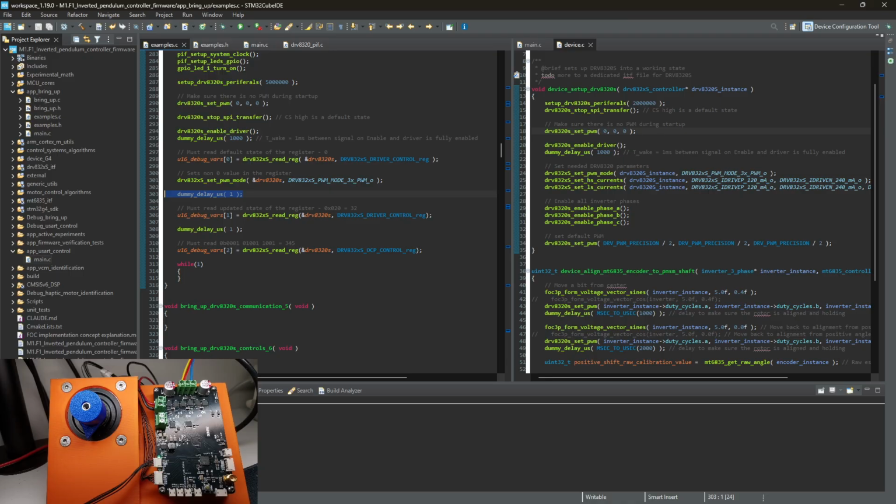The point for command lines is, for example, when you want to start building your project with CMake, which is a big deal because it will be much easier to implement GitHub Actions and do hardware in the loop testing. When you push a commit to GitHub, it automatically downloads everything to your test computer, which builds the code, tests the code, flashes it to the device, then tests it using another device, and then returns the build results, which is a very complicated and advanced workflow.